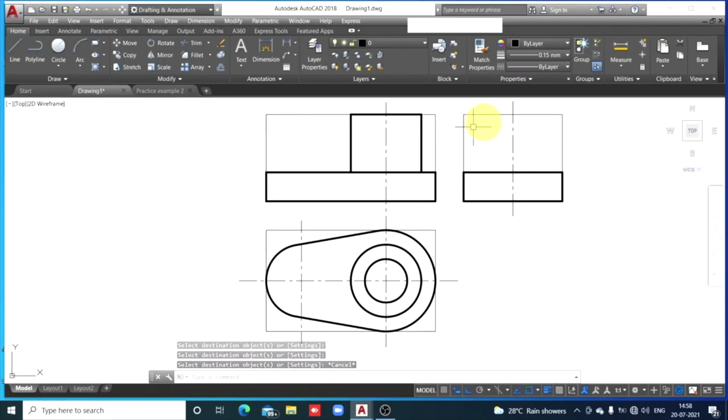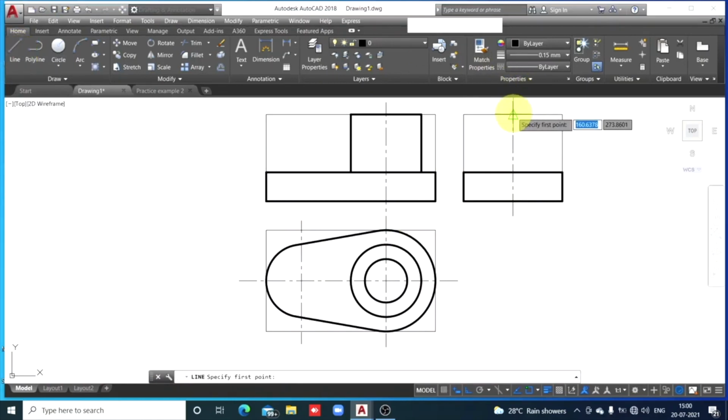Cylinder appears a rectangle in the side view also, rectangle of height 40. Select or click on line command. From midpoint, 25, enter. So at distance 25 millimeters the start point is. So from this start point, this is that vertical edge of the rectangle.